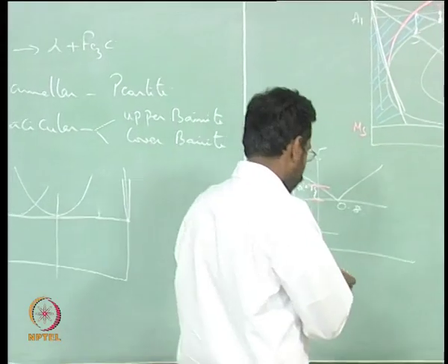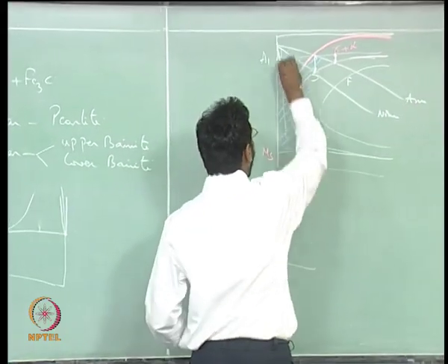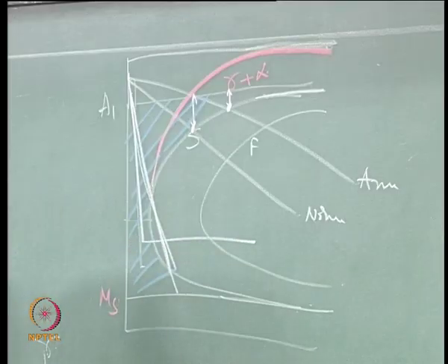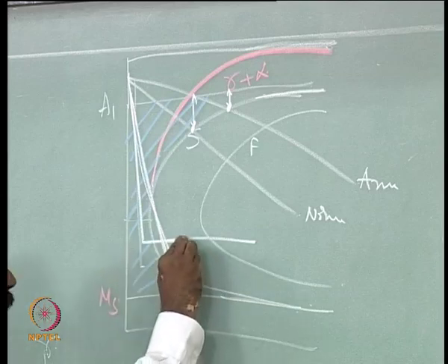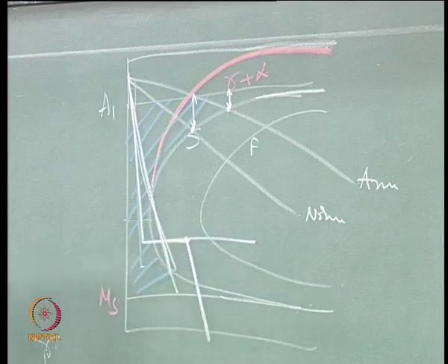Instead, if I cool it to a high temperature like this and hold it there, then the same gamma would undergo a bainitic transformation, whether upper bainite or lower bainite. If I hold it for a shorter time and then cool it, then you will get what?